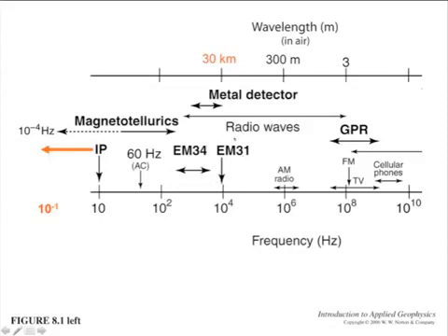Now, what about the names of these instruments? There's the EM31, which is what we used, I think it might have been the 1992 class, to profile across the Pahrump Valley Fault, and we found shallow conductivity anomalies. It was with an EM31. That's a very nice conductivity electromagnetic instrument.